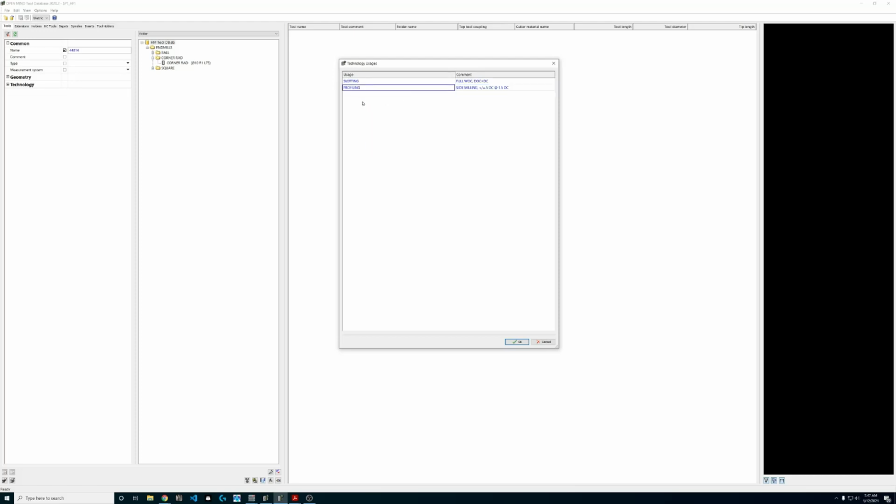In reality, most people aren't taking a half cutter width step over because in most machining centers and most tool holding and work holding, that's not super practical or efficient anymore, but that's what they're giving us. And lastly, they have some high speed machining. So we're just going to say high speed cutting, and this is the absolute opposite direction where they're saying that's going to be less than or equal to 0.05 DC, which now that's the other way. That might be great for cutting tools in steel, but for an aluminum tool, we're going to take more than just 5% of the cutter diameter step over because we can easily do that. And they're saying at less than or equal to 2 times DC.